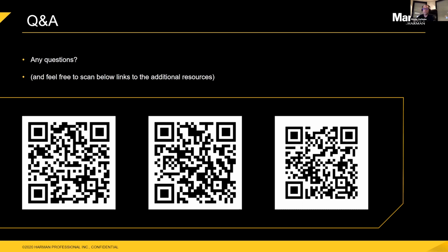Very good question. Yes, so when you patch a fixture in hybrid mode, which has that 16-bit dimmer, the dimmer always controls the fixture. So no matter if the P3 switch channel is set to DMX or if it's set to video, no matter if you're showing DMX or pixel mapping from the desk or from the video from the media server, the intensity channel always controls the fixture. So no matter where you toggle with the P3 switch, the dimmer intensity channel always controls the fixture. So yes.